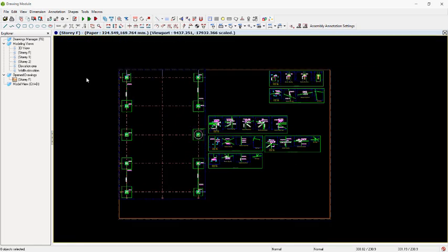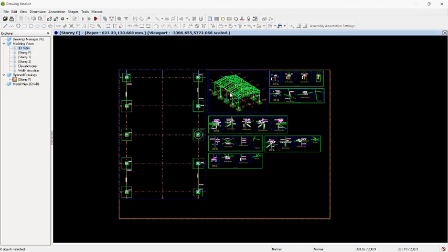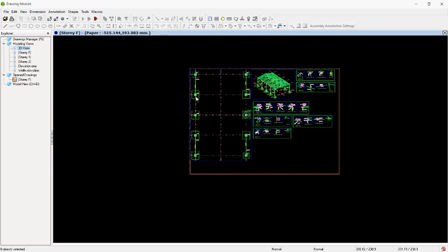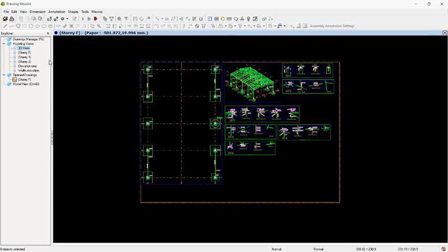So you can still bring it out if you wish. You select it, right click on create again. So you see this one is less busy now. Okay, so having created this, we are good to go, and this is being created under story foundations. All right, under story foundations. So you have to take note of that. So this has been saved.